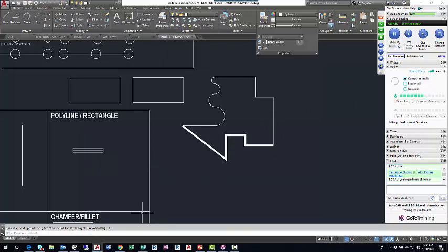But that's what qualifies Polyline to be referred to as an advanced draw command, because it does have these command line options. Now you should be aware, once you change the width of your polyline, all future polylines will stay with the changed width until you change it back. So if I go polyline, left click, I'm drawing again this 2-inch thick polyline. I'll click width on the command line and I'll make the new width 0. 0 is the default width. Enter. For starting and for ending, I'll do 0, enter, and now I've gotten back to, oops, I think I ended the command. Let's see, there we go. So even though I ended the command, I did change my width back to 0.